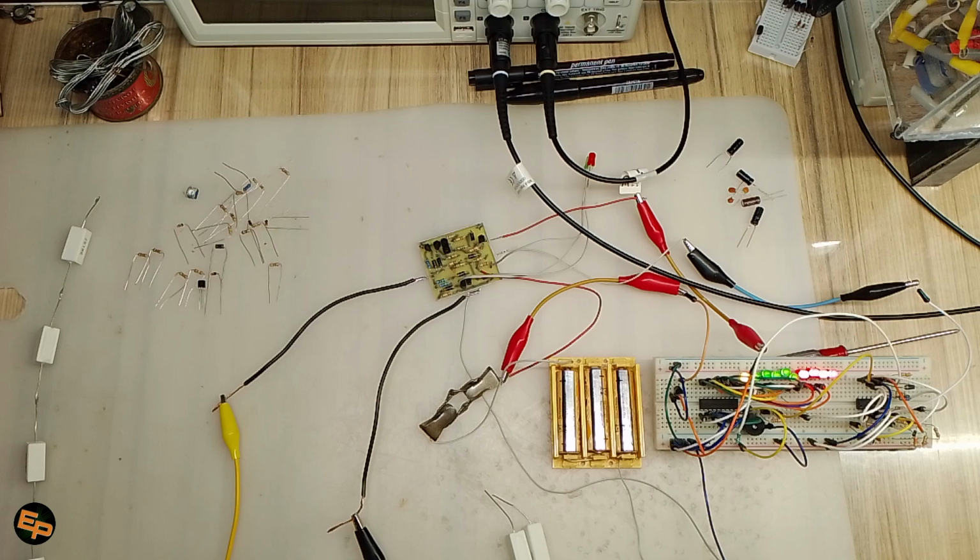And initially, with this long ground wire, we see here on the breadboard that I have 10 LEDs. It's basically a VU-meter. Okay, and I was having all of these LEDs turn on, like you can see here, in spite of the fact that I shouldn't have had it. But again, because of these parasitic signals that were induced or coupled into my ground wire, the second circuit was seeing a much bigger input signal than it should have seen.